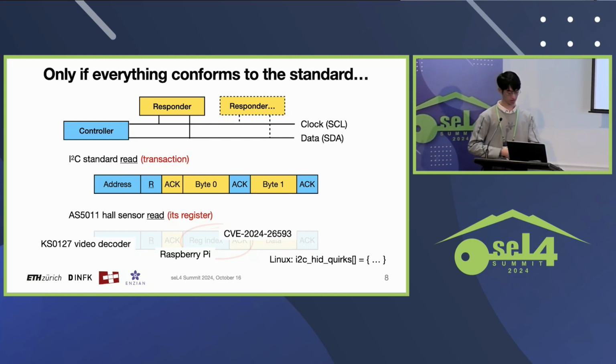And as you can imagine, this is a problem for verification. How are we going to model and verify buggy hardware? Additionally, unlike other devices that have a point-to-point connection with the BMC, the nature of a shared bus means that if one device fails, the system may just stop working because of interference between those devices. And since we are building a trustworthy I2C stack for the BMC, we want to ensure that the system works even if there are multiple devices interacting with each other.